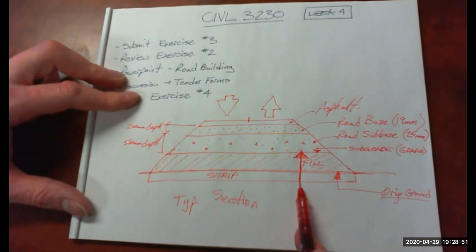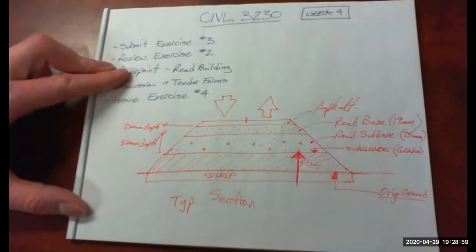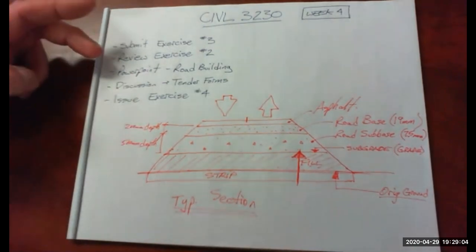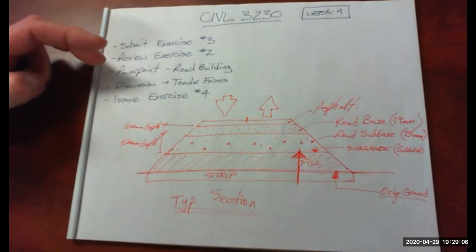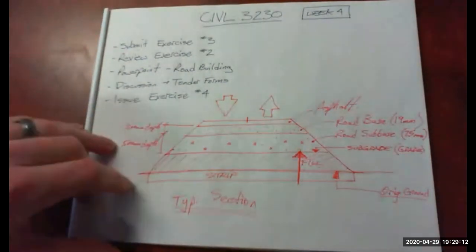So the bottom of your stripping up to the bottom of your subbase, which is subgrade. Does that make sense? So this would be a fill section.